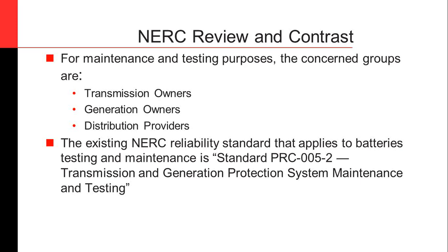And then, okay, there were some correction tables, I think, a few slides ago. Are these from the IEEE 450 standard? Yes, they're contained in both the IEEE 450 as well as the IEEE 1188. 450 is for the vented lead acid or flooded cells, and 1188 is for the valve regulated lead acid. I also forgot to mention, we're not really talking about NiCad batteries. There might be some users of NiCad batteries out there. That guide is IEEE 1106. But yes, the two tables are contained in both of those IEEE guides.